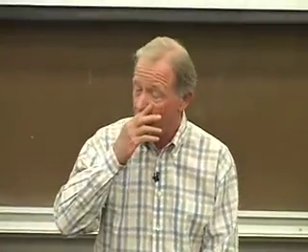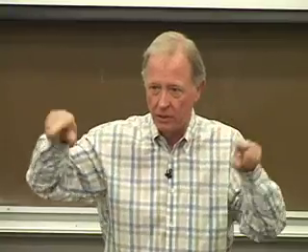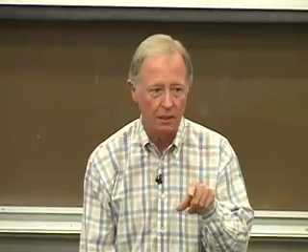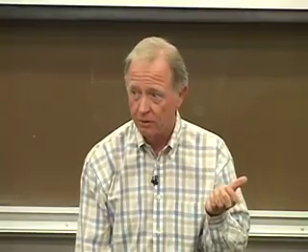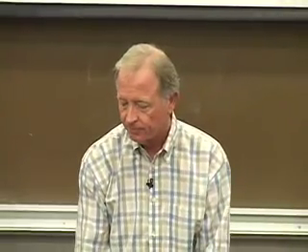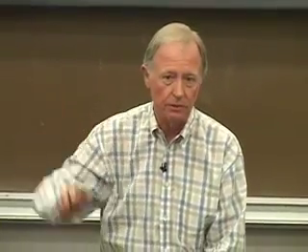And we learned to take a complex process. When you make mass balances, you always draw the little control volume, and you make the balance across anything that's crossing that control volume, except if something's going on inside the control volume, such as reaction. You need to take that into account, because you can either be consuming or producing a component. We also have units that are connected back, a recycle stream. So you learned how to handle recycle streams. And then after we talked about those mass balances, that led us into what?